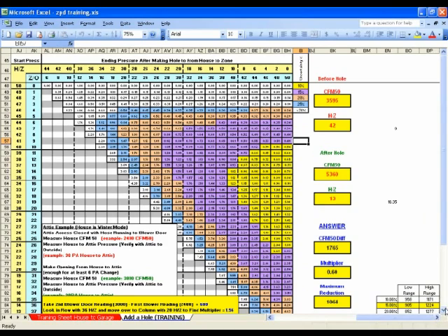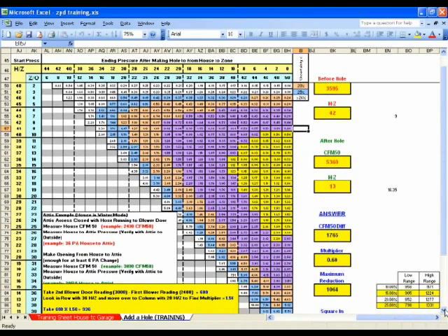Over towards the bottom corner of this chart, it shows you, based on your uncertainty, what the range is. So in this case, it's showing that our maximum reduction is about 1064. We've got a 15% uncertainty. So really what that's telling us is we're somewhere between 900 and about 1225 CFM is our potential. That's about what our uncertainty is, plus or minus 15% in this example.